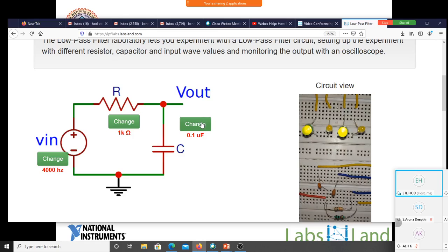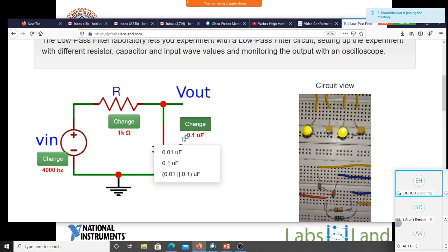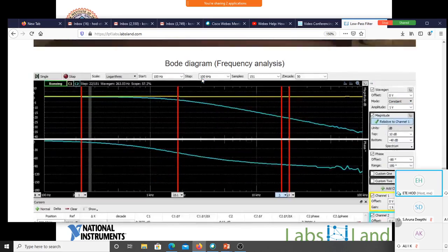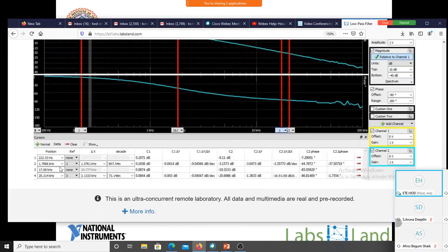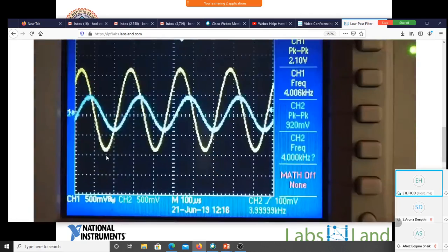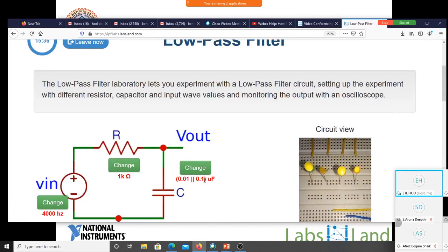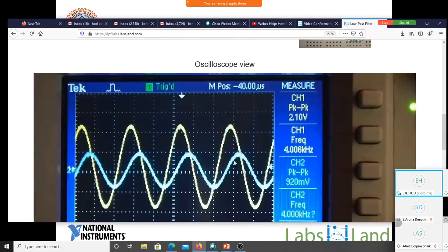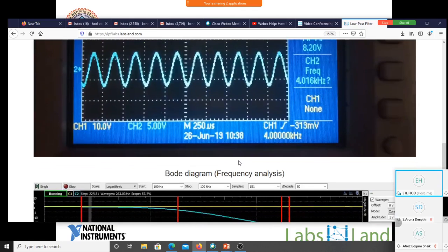Suppose if I make this again, let us make this equal to 0.01. Hardly is there much variation that will happen here. It was 1.79 kilohertz. You can see it's almost close to that. What we have is, since it is 0.1 and 0.2, this is just 0.11 that gets added. So there is hardly any change in the frequency response of this. And of course here also it comes very close to it.